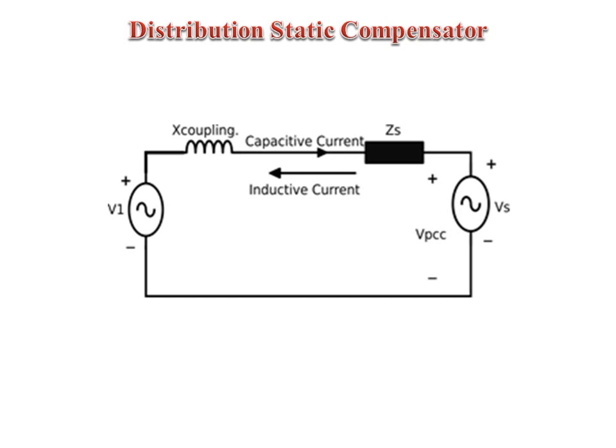Thus, static synchronous compensator, which is shunt connection, is connected to three-phase distribution system with non-linear or unbalanced load. This STATCOM can provide shunt compensation by injecting current in the distribution system that varies linearly with the voltage. This distribution static compensator consists of voltage source inverter, DC link device required for energy storage, filters for eliminating the ripples present at the point of common coupling, and inductor or coupling transformer.